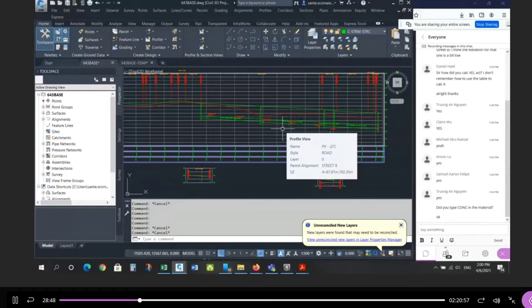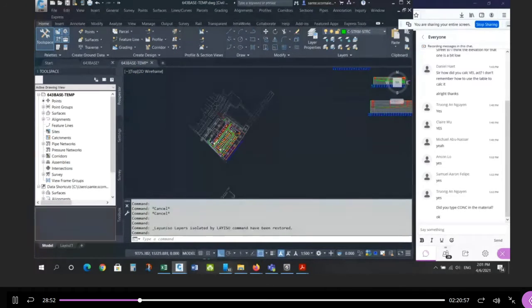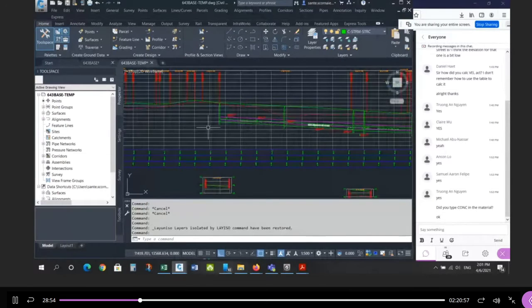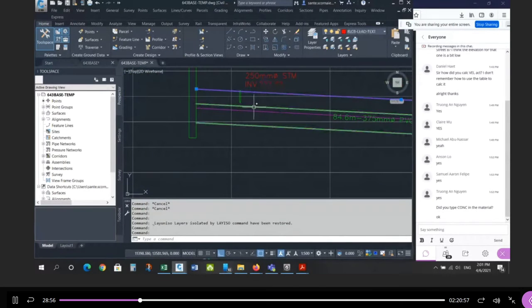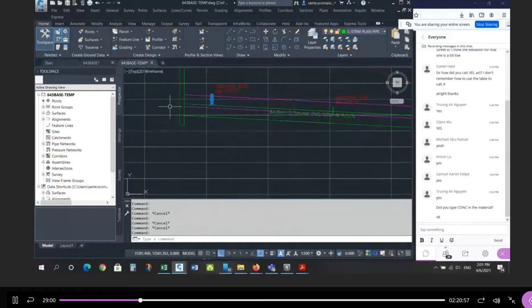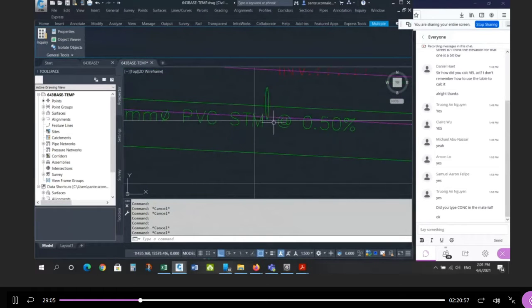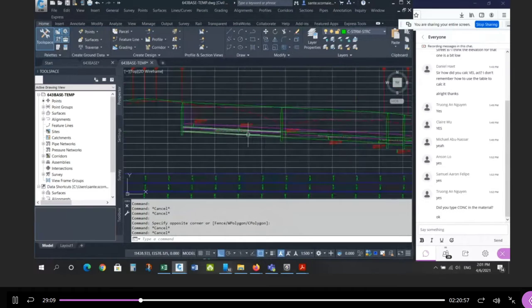Now that I've pushed the sewer system down, let's see if I've resolved any of those. So 5 are no good. Let's see how many are fixed now. So the pipe is lower, right? So the pipe used to be up here, and now it's way down here. So this is good. It always was. The next one didn't work by just a little bit, but now it's way above the invert of this pipe. So that one works. So I've resolved one of the issues.